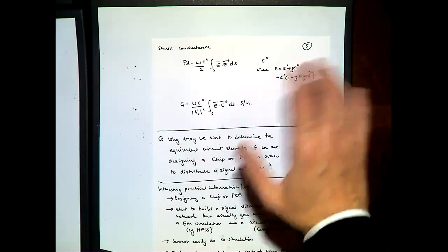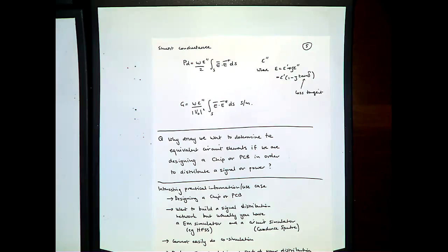We briefly reiterated all the work that we had done in the past about loss tangents. There I've got the E double dash written up there, which is the complex component of the permittivity constant. What I'm showing you here is that in the data sheet, when you look at various materials, usually what people indicate is the relative permittivity and the loss tangent.